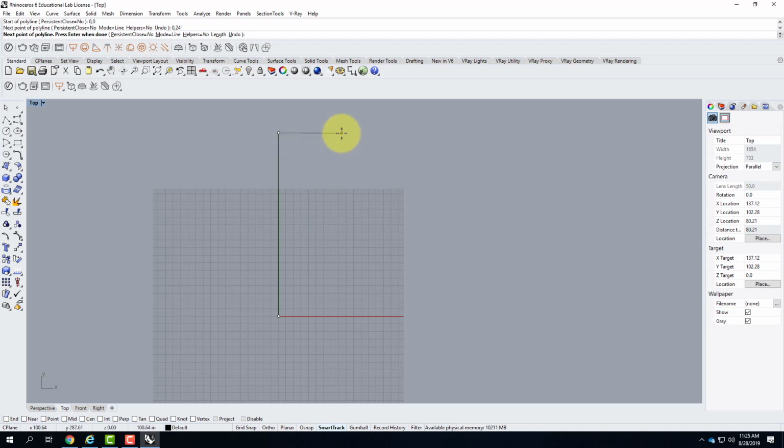The next piece is I want a line that is 12 feet over from this point. It's over here somewhere. And it's still up the 24 feet. If I'm using these absolute coordinates, so this is relative to the origin or relative to 0, 0, this point is a little bit harder to come up with. In this scenario, I have to go in the x direction 12 feet, and then in the y direction 24 feet.